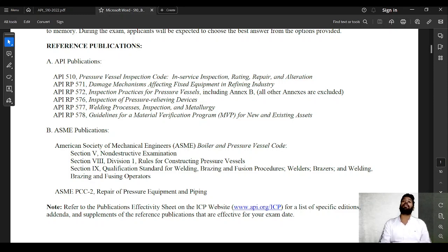then there are multiple things that can happen, because if the material is wrong for service, then some different kinds of degradation mechanism can be taken into picture. This will ruin the service life of the component. So whenever we are using some component in a critical area, some material verification needs to be done. This is generally going to be limited to PMI or mill test certificate, so some form of material verification program has to be set in place.